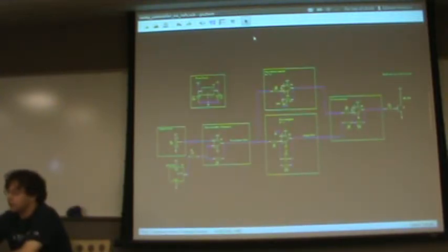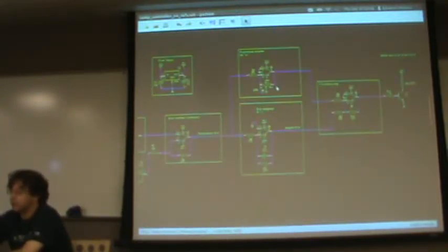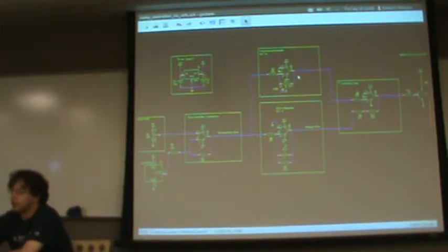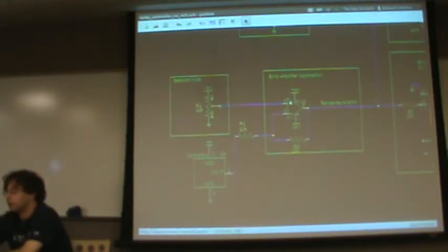Let's see, other stuff. One other thing that you can do that's going to be important if you're designing for a circuit board, a lot of times when you're dealing with especially op amps or logic gates, you'll see that there are 4 of these in one chip. So right now I've got each of these op amps is specified as a separate chip, and this is using pins 1, 2, 3, and 4.